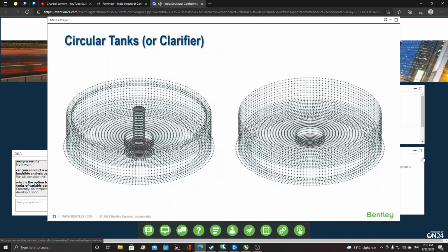Now, just to reconfirm, from the same clarifier modeling tool, you can model a full structure which will have the launder, the support column, the foundation, and the base slab being inclined. Or in case you need a smaller, cleaner model, such as this, with no launder, maybe a flat bottom slab with no support column, it's possible to do that. So the same modeling tool can produce this and can produce this as well.